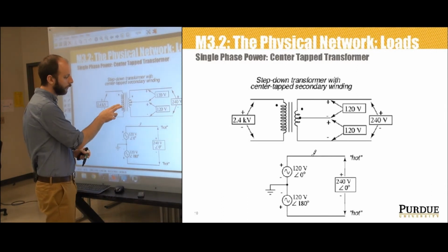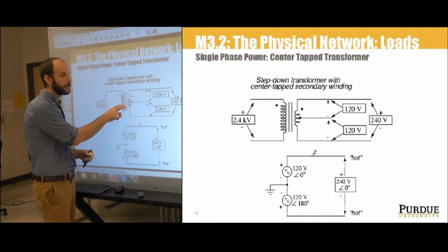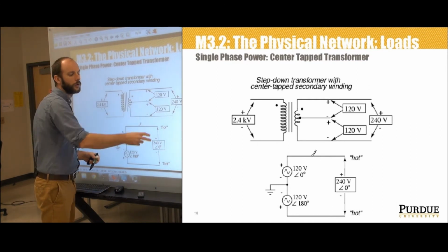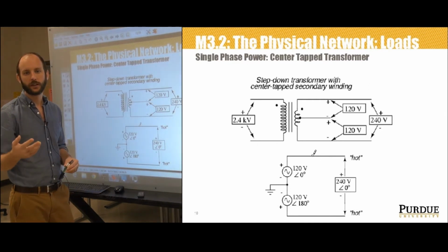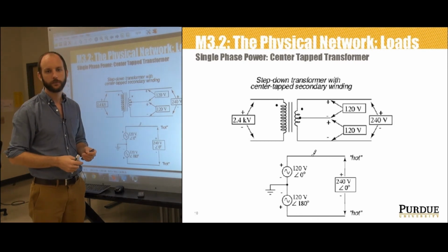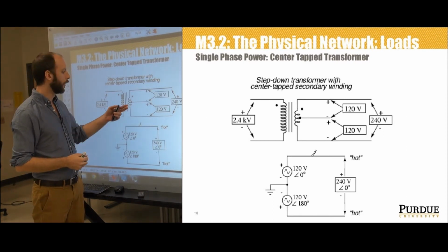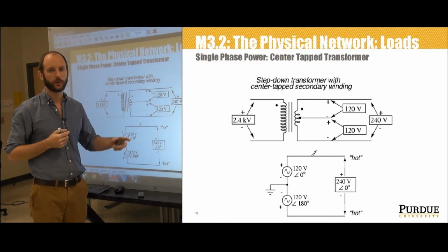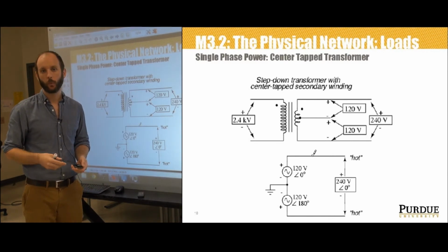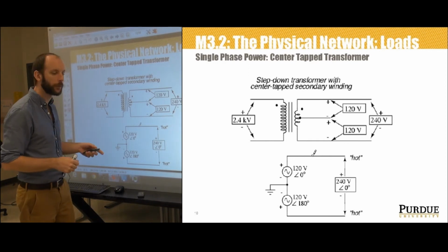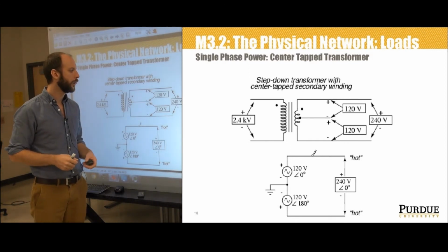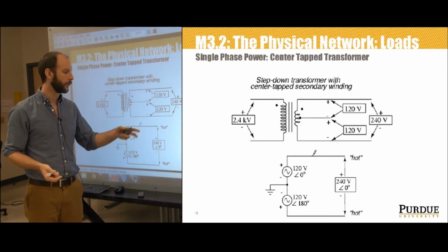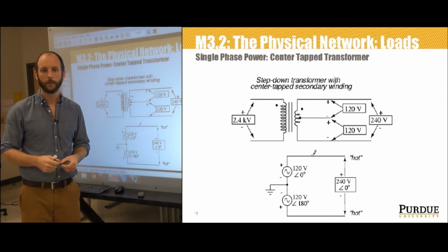And these are all coming off one transformer phase. That means 120, 120, and 240 volts. Those are all in phase, right? They're all in phase. So the resultant name of this circuit is 120 single phase, 240 single phase, 120, 240, a lot of times people will call it. But it's 120 single phase, 240 single phase. The voltages are in phase with one another.